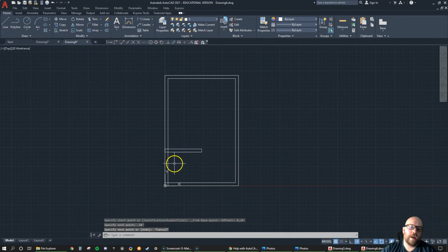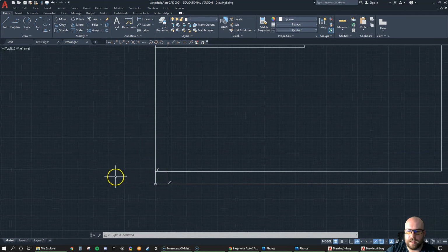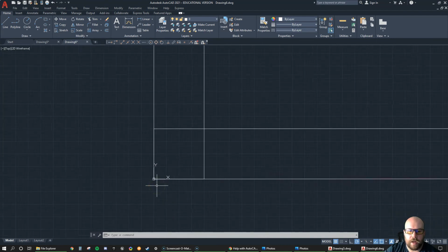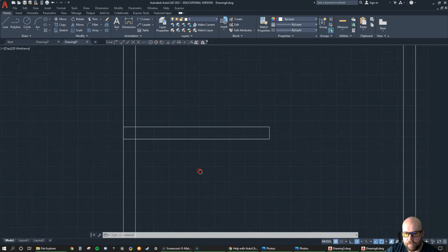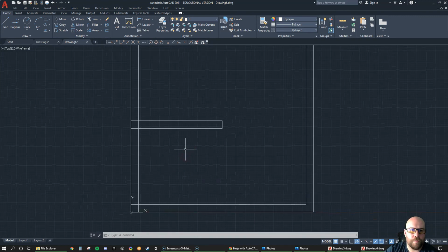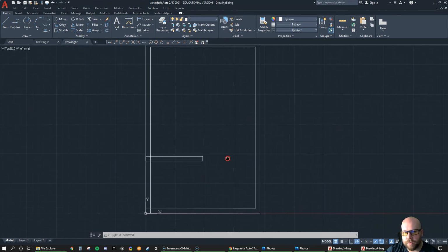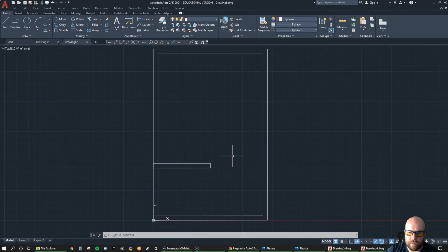Okay, now from here, you have a couple different options for editing this thing. Okay, we have these different walls that are overlapping. Now there's a couple options, and one of them can be a little bit glitchy. Once you start editing things and lines move around and stuff, but I'll show you that one first. So ML edit is one of them, multi-line edit.